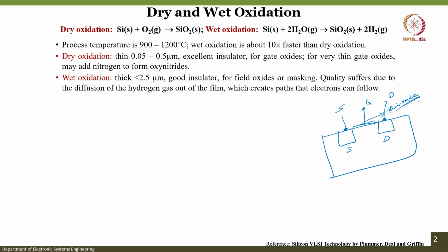So now one can guess, out of this dry oxidation and wet oxidation, which one gives you excellent oxide material. So just think about it. What gives is dry oxidation, because you see only silicon dioxide is getting formed. Here, along with silicon dioxide there is another product, hydrogen, correct. Now it is in gaseous form, it has to leave that particular reaction and go out. What happens is, it will create holes in the oxide films that are formed and then leave. Because of that, the material property will be compromised compared to the dry oxidation.